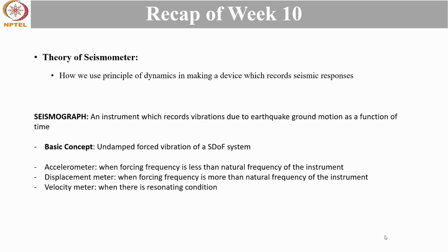On the other end, when the forcing frequency is larger than the natural frequency of the instrument, the seismograph acts as a displacement meter, and under resonating conditions, it acts as a velocity meter.